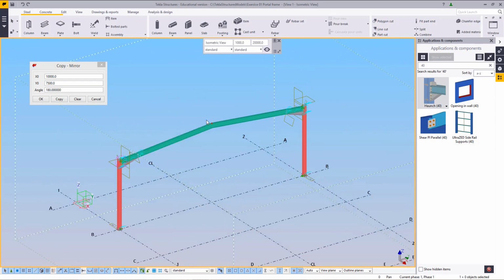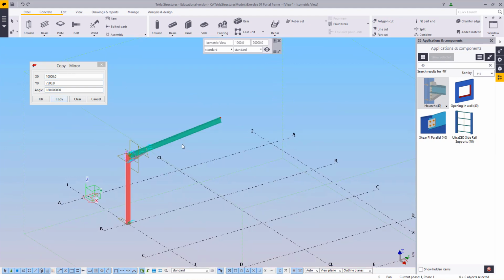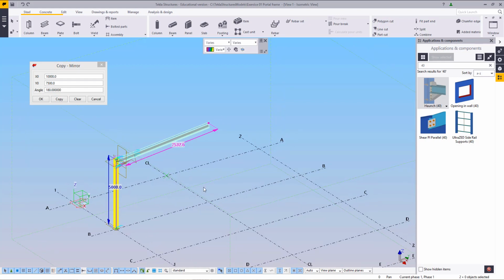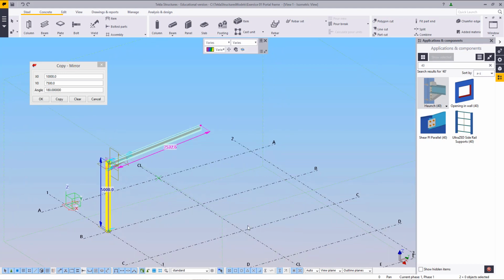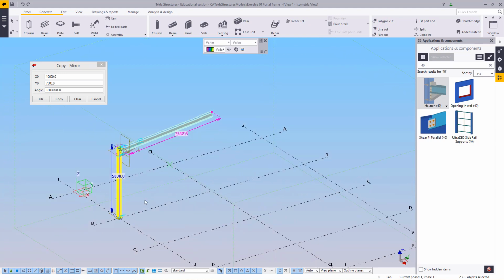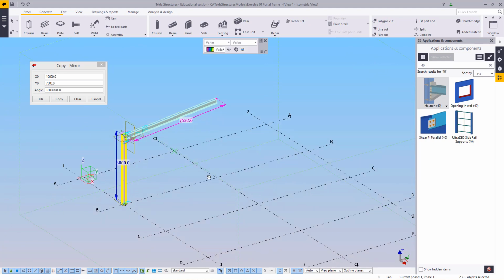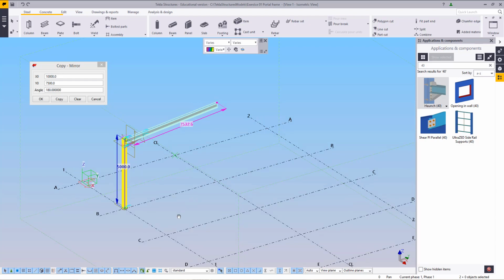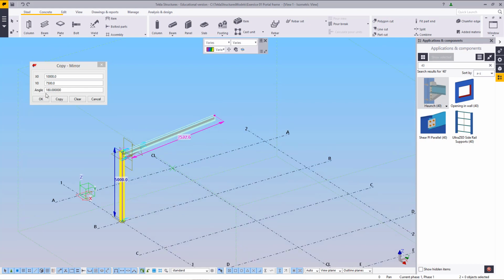Now this does not have to be done in a plan view. It really doesn't matter, as long as the line you are using for your center is on your grid lines view. So in other words, any line that's in the XY plane can be used, doesn't matter what the angle or where it is, but a line that only goes in the Z direction won't function. Just something to keep in mind for a later time.